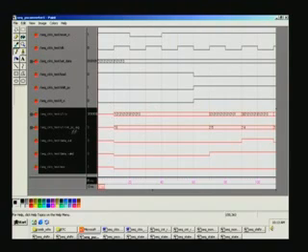And this is the counter to keep track of the number of bits. Now you need to send 16 bits, so it is initialized to 16 here, and for every bit going out it will be decremented, as you can see, going to 15 here, 14 here. Why is there a long gap? We have first loaded this value by activating this high, and it goes low only here, and then simultaneously we make the shift control high, so that with the arrival of the next positive edge of the clock, it starts and the counter starts decrementing, as well as it outputs the value.